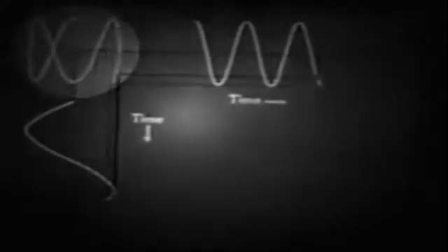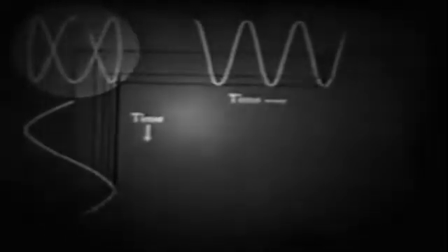This figure, for example, is the result of a frequency ratio of 1 to 3, with the horizontal and vertical voltages 90 degrees out of phase. Even complex patterns can be analyzed by graphical methods. By reference to standard charts, frequency determination, phase relationships, and many other characteristics can be determined.